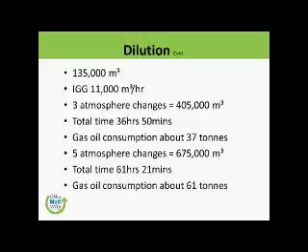So you remember, as compared to a very small gas oil or low sulfur gas oil burning, if you are going to burn it continuously for 61 hours and your vessel cannot be chartered for the next 61 hours, then you will really be sweating and you will be throwing things around.